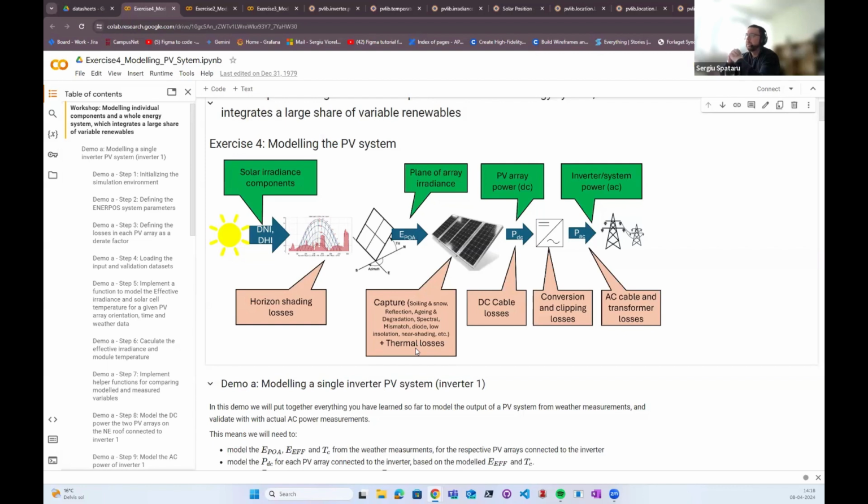So you'll need to either try different degradation rates, or look at similar systems in the area, or read the literature for the specific climate that you have, to find the degradation rate. It also depends on the type of solar cell. Thin films usually degrade faster than crystalline ones. Then, adjacent to aging, there are other failure mechanisms that degrade the panels beyond the assumed degradation rate. And that can happen.